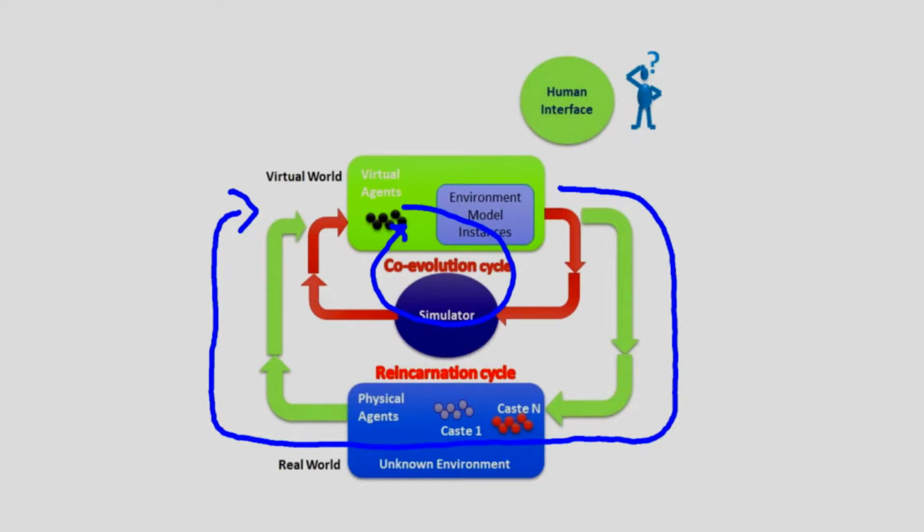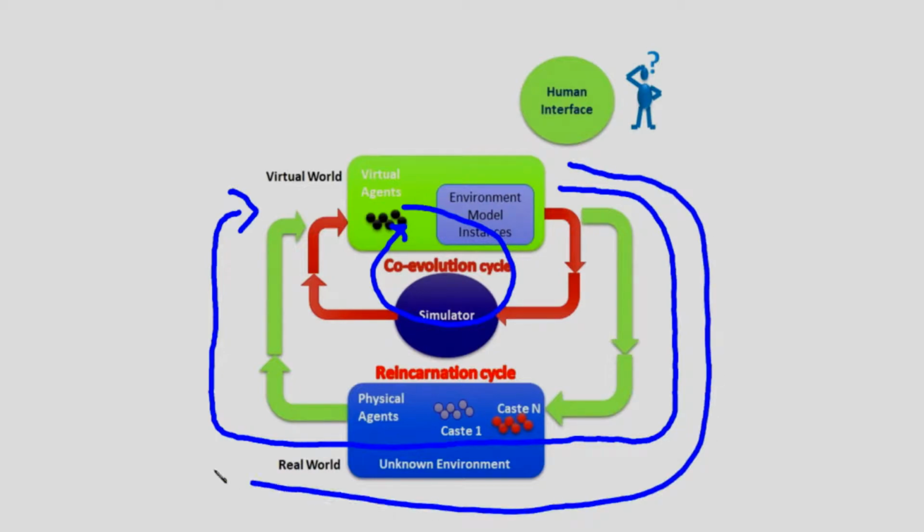And then we use these models in the second step in the simulator to optimize the sensor models, the virtual sensors, for these more likely models of reality. And again, when we have then the best possible models, we make a second round through reality. And this ratio, the number of times we go through a simulation loop and the number of times we go through reality, in practice can be quite large. Think about maybe 1,000 iterations in software versus 1 iteration in reality. So this is something that we tried, and that actually works for a number of realistic problems.